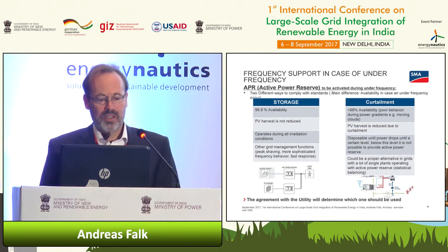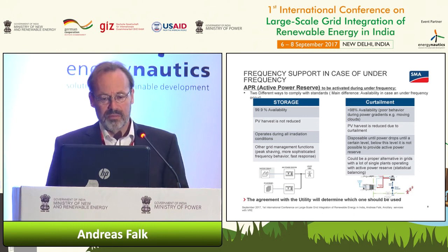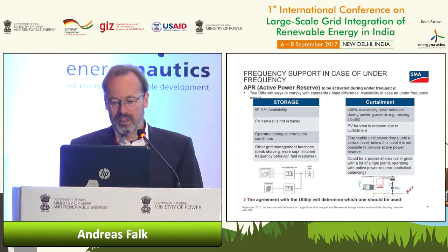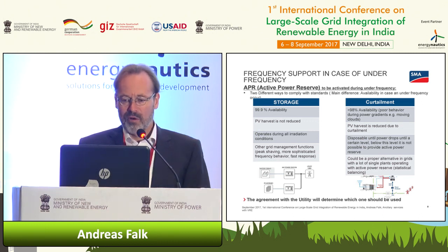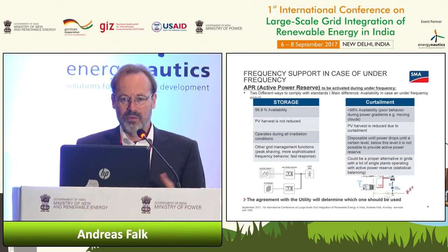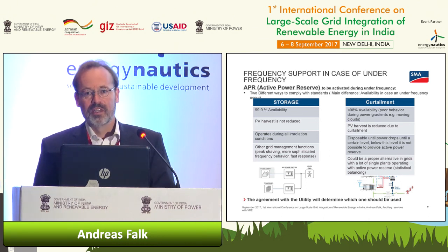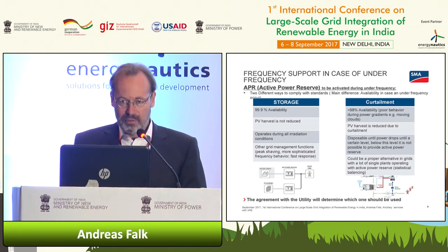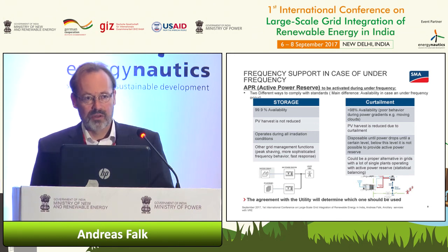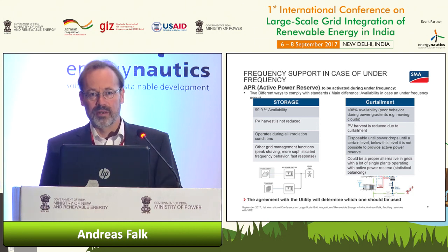It is important to say that the active power reserve for renewable parks is only activatable in case the power is above a certain limit. When the power falls below 20%, for example, it is no longer possible to generate active power reserve because the tolerances are too high.